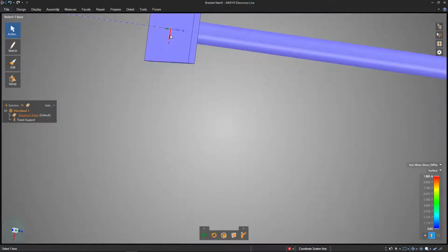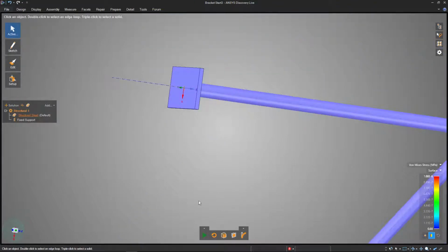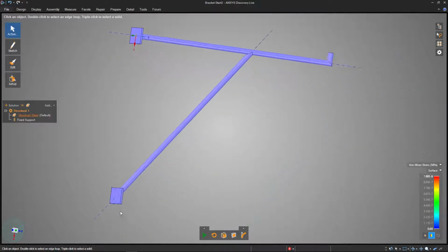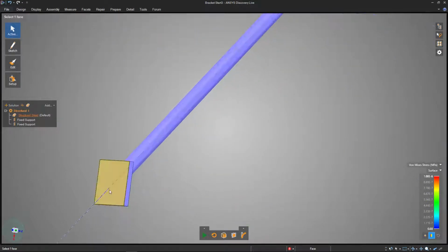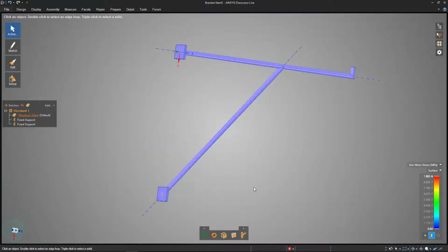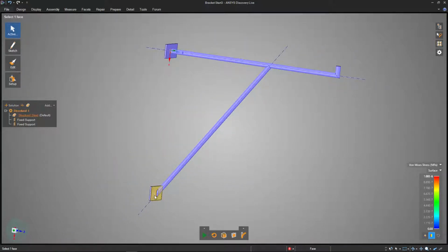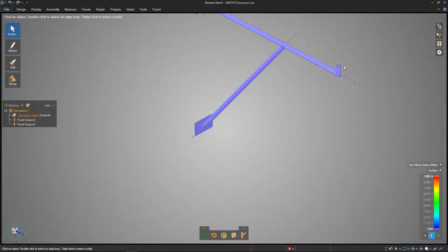And if we look at it, it's hiding under the origin there. It puts a little icon on that face. It'll be easier to see it down here, which indicates that it's actually a fixed face now in the simulation. And we can even see that when we pivot away, it lets us know where that is. The second thing that we needed was to tell it where the force is, both magnitude and direction, since it's a vector. Part of the reason that we put this object out here was so we'd have a nice face to put the force on.